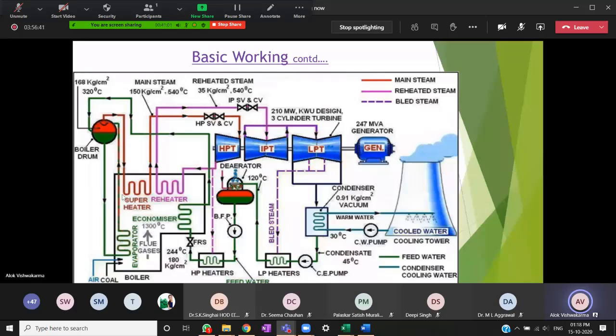This is the boiler part. These are tubes, superheater tubes. Steam is going through, getting some additional heat, and then now if you can see, this is the main steam. The temperature of this is around 540 degrees Celsius for a 200 megawatt unit, and it differs for a 660 megawatt unit, where it is around 600 degrees Celsius. So high temperature. Pressure is also 150 kg per square centimeter for this 210 megawatt unit. For higher size units, this pressure will go higher, 170, 180 like this. So it is high temperature, high pressure steam.